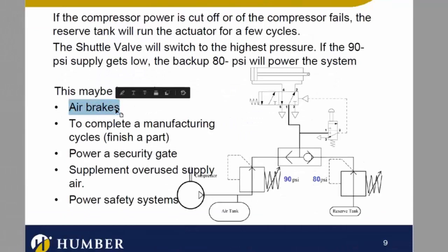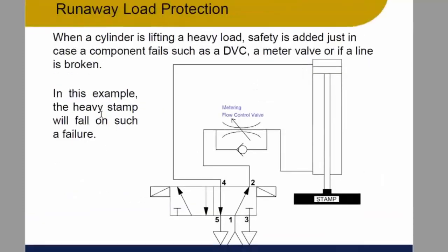Air brakes, which are pretty cool, are all fail-safe for sure. They're fail-safe in a way that if the pressurized air disappears, a spring takes over and activates the brake. Actually, the only way to release the brakes is to pressurize the system. If you pressurize the system, then the brakes release. When you put your foot on the brake, it actually bleeds air out of the brake system and allows the springs to take over. Again, fail-safe design. It's important that you understand how to do this in your application when you're out there in the field designing this stuff.